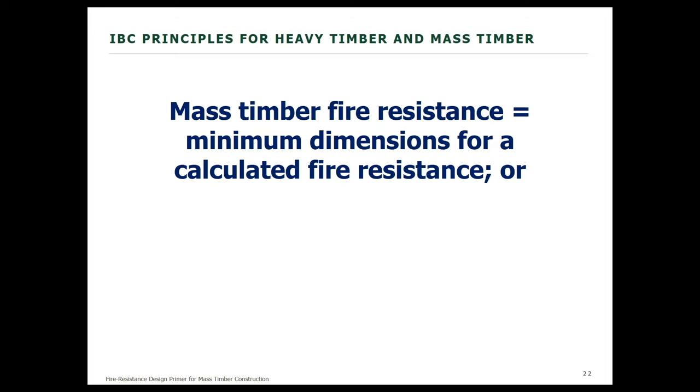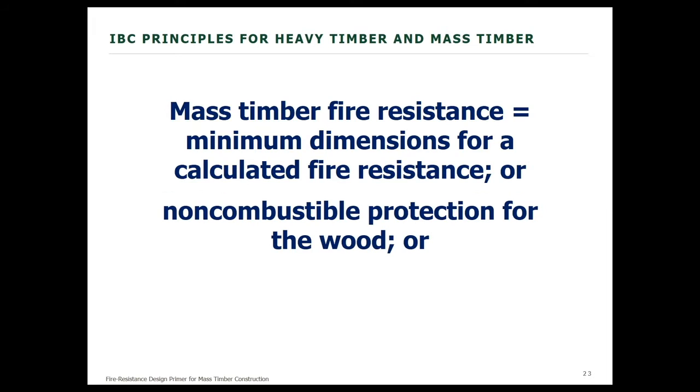So you can remember that you can accomplish the total required fire resistance by sizing the member so that all the fire resistance is accomplished through the calculation method of fire resistance of exposed timber, a method we will discuss in more detail in a moment.